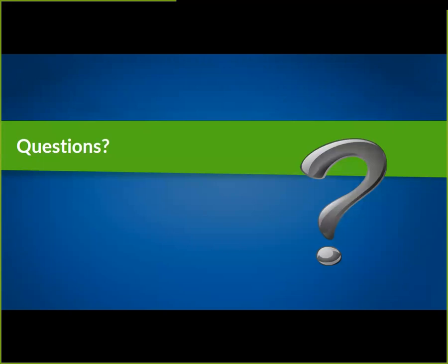Yeah, that's a good question. So I'll try to answer that one maybe in a slightly different way. The things that you've mentioned, like redevelopment and infill, are all important things to consider when you're developing a minimum building elevation approach. Every time you incrementally fill in a particular lot because somebody wants to mitigate flooding on their property, or is told by the municipality that you must be above elevation X, you end up deleting some floodplain storage for each lot individually. So as you move forward, that minimum building elevation number could actually creep up